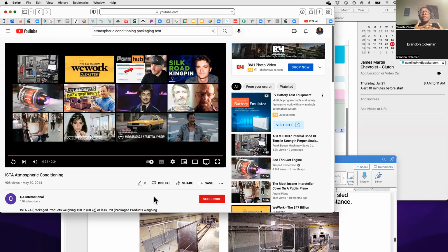So it could be a food that you want to ask, how does this food or this package perform after 18 months? And there's a data table you can go to and say, okay, I want to simulate this having been out in a warehouse for 18 months, and you pick the numbers on that table, set that chamber, and then you let it sit in that chamber for however long it's specified in your test protocol to condition it and get it to equilibrium.